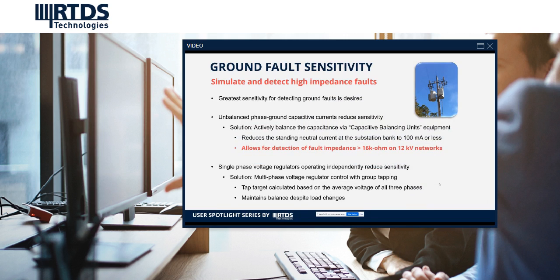So one of the big advantages of this technology is its sensitivity to ground faults. It's much higher than other methods of handling the neutral in a power system. So we're simulating and detecting very high impedance faults. There are some side effects that reduce the ground fault sensitivity though, so those must be addressed to increase it to be as great as possible.